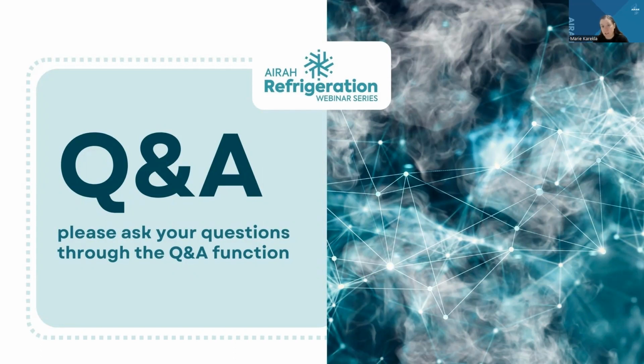Yeah, thank you, Andrew. And another one here is, do you recommend performing air leakage testing for cold freezer rooms as part of commissioning? If so, any particular air leakage rates at certain pressures as good practice can be used? For air conditioning, yes, it's standard practice, but I'm not aware that this is used for freezers and so on. But Jonathan, maybe you can help me out on that. I know air conditioning, it is a practice, but for cool rooms and freezers, have you seen that been applied to air leakage tests?